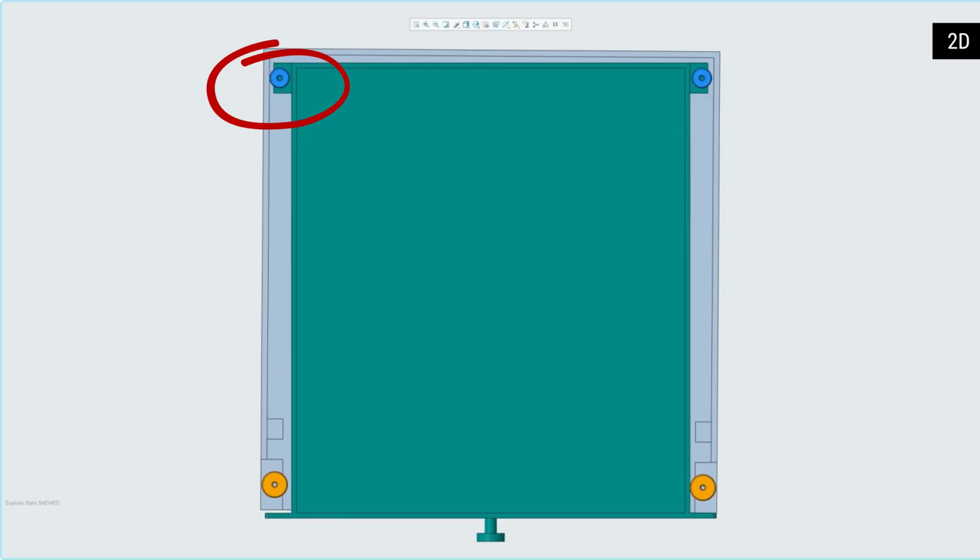This allows for angular misalignment of the drawer, which could create interference with neighboring drawers or lead to other poor user experiences. We can check that by creating a tolerance stack, which evaluates the clearance in Y direction between the edge of drawer front and side of the frame.